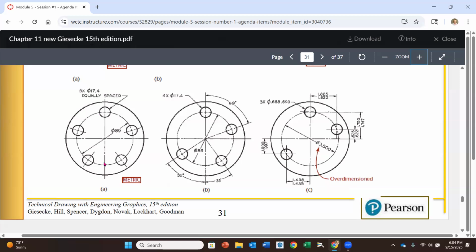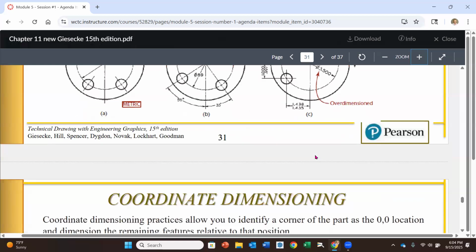So you would call out the size of the center circle here, which we call a bolt circle, for which all of those share, and they're on the same bolt circle. And then you would just say that those are whatever size they are, evenly spaced on that bolt circle. Another way you can call it out, if they're not evenly spaced, you can put dimensions like angles between them, or you can call them out so that you have the X and Y locations from the center of the part. So a couple different ways that we can call those out.